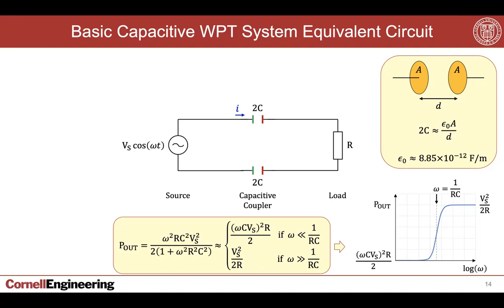And you can essentially think of the power being delivered as by first computing the current that's going through those capacitors, which is basically the voltage applied divided by the impedance of that capacitance, which in magnitude is basically 1 over omega C. And then I squared R gives you the power that's delivered, and the factor of 2 comes because you've got a sinusoidal source in this case.